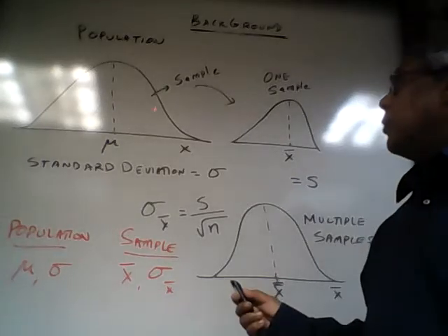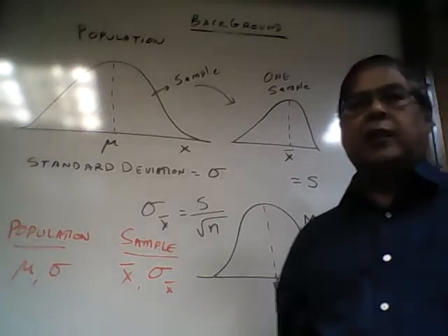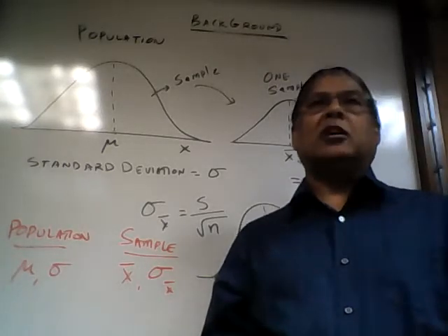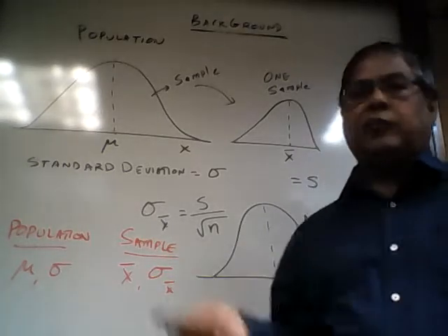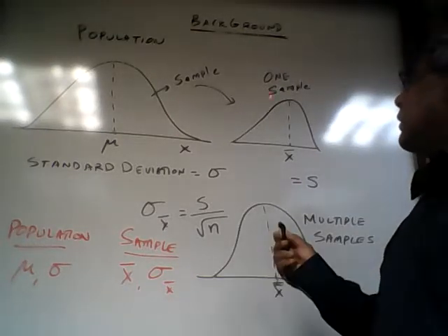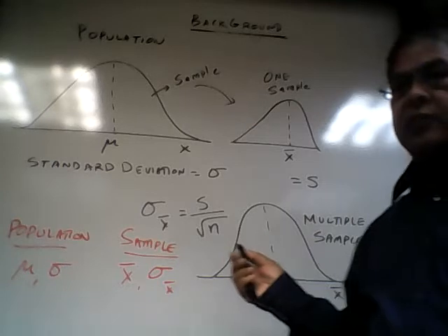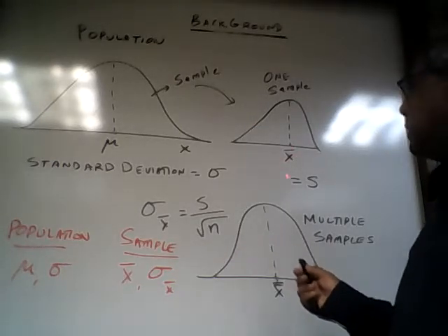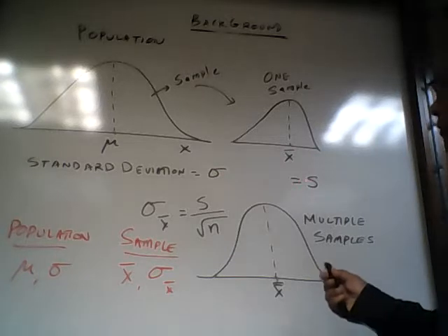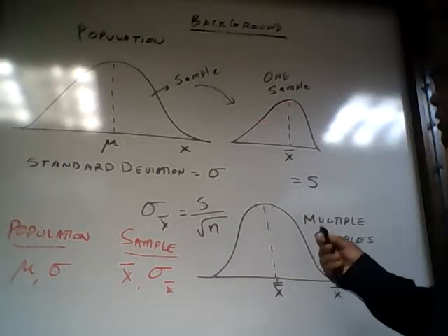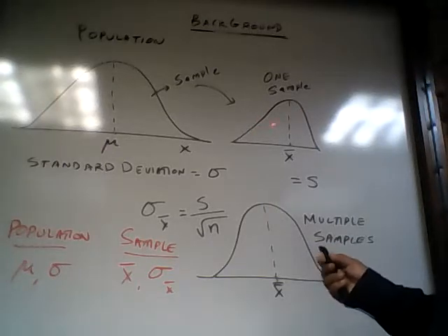Now, if I take a sample from this population, the sample size is very small, somewhere between 10 to 20 bearings. But the population refers to millions of bearings. So if I take 10 to 20 bearings and do one sample test, finding out the mean value is called X bar, and the standard deviation is called S. And keep in mind, the distribution is not quite a normal distribution here. It is not a normal distribution.